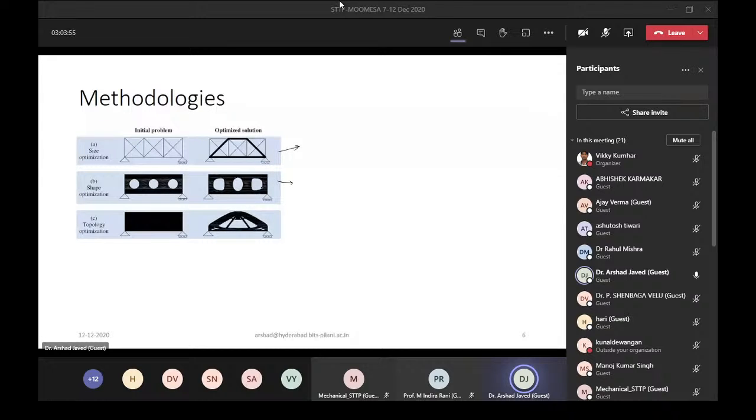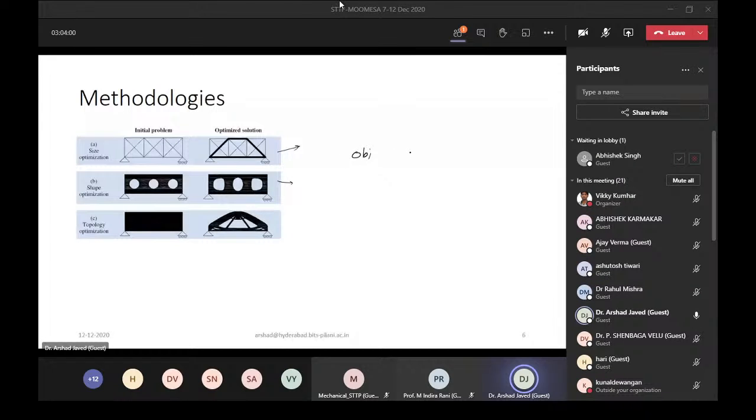Suppose in this problem, in shape optimization, if you wanted to define it, the objective function will be what? Let us say deflection is a function of shape, and shape is a function of parameters x1, x2 to xn. Different Bezier and B-spline curves can be defining these shapes. This is the objective function, deflection, and then somewhere here you will calculate the mass into this one, okay, and then the parameters will be x1, x2 and so on. And if it is a constraint, subject to,